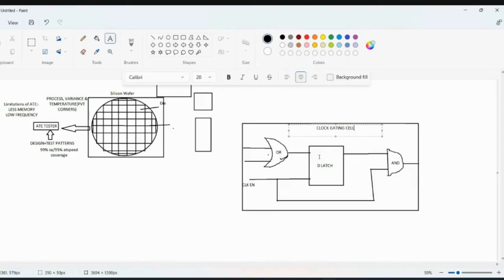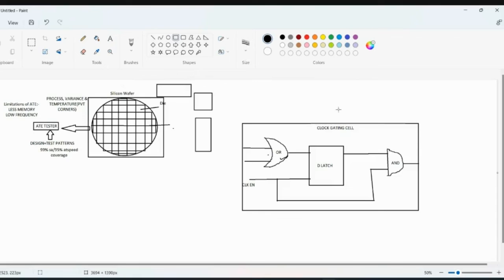So, in order to remove or eradicate any sort of glitches, we have a proper latch, and this latch will take care of any ripples coming in this way till this way. Once we get a clock to this part, you have no glitches. And if there is a possibility of glitch outside this clock gating cell, you can just have a clock synchronizer at the output of this particular clock gating cell. You just add a clock synchronizer.